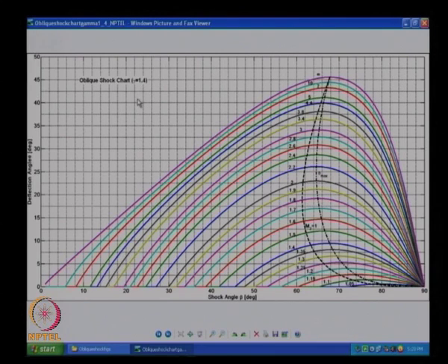The plot looks like this, it seems like for every deflection angle there is double value for any given Mach number. These values written here 1.1, 1.2, 1.4, all this up to infinity, Mach number infinity, everything, it seems to be an inverted U shaped curve, which is for every deflection angle, let us say I pick 10 degrees and I go for say Mach 2, I could have an angle of the order of 39 degrees, or I could have an angle of the order of 84 degrees or so. Okay. I could have two different values like this.